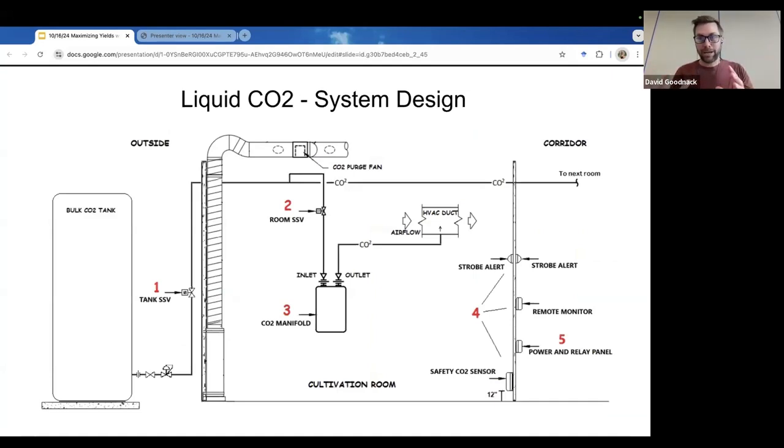So this started out with Plant CO2 just manufacturing that CO2 enrichment manifold where no one did, and it slowly grew to be a full scope provider. So I can provide the tank, the supply, the CO2 distribution. I provide kits for that. So I design those kits. It's all low density polyethylene tubing that's meant for CO2 and those pressures. And it has kind of quick connect, kind of like doing PEX tubing in your house. If you've ever done that, it's just push in, kind of like a SharkBite. So it can be self-install based on the kits that I design.